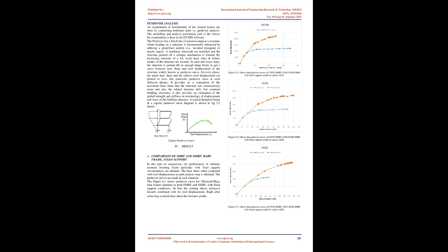3. Methodology. Building configurations and design details. A maximum of 12 structural frames are designed with different numbers of stories, two different quantities of bays, and two kinds of infill wall configurations. A detailed illustration of all the types of frames made in this study is given in Table 3.1. The height of story is 3.5 m and the width of bay is 4 m. That is the same for the rest of the frames.